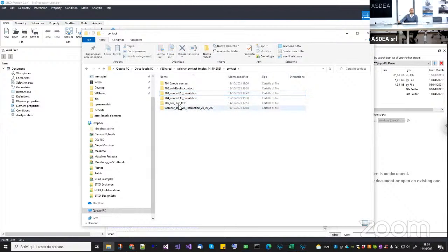and now you can do a soil-pile interaction test, which is basically the same that we have done in the past webinar. But in the past webinar, we were using the beam contact 3D model, and that model works fine, but it takes a lot to converge, so it has many convergence issues. And I will show you how much faster it can be with this new element.